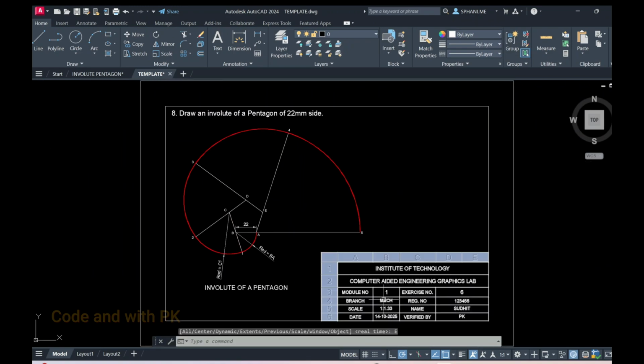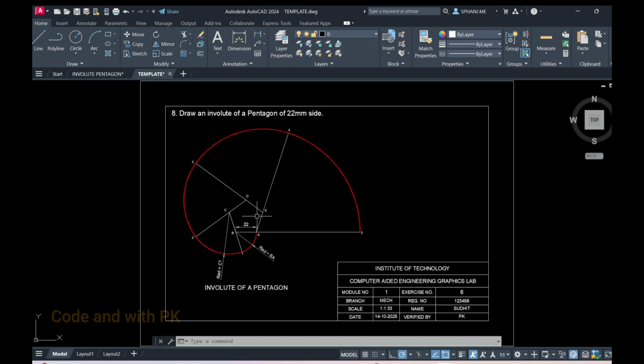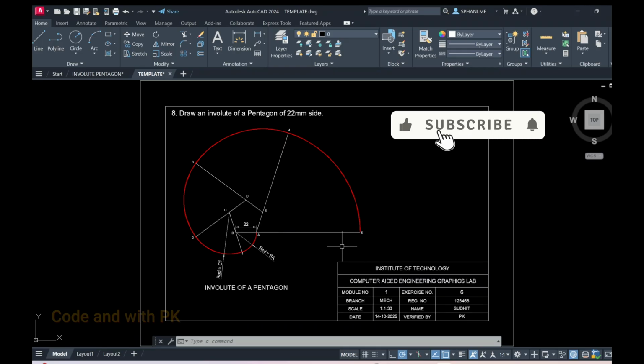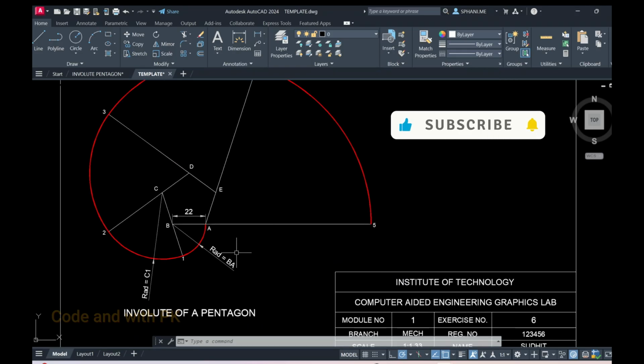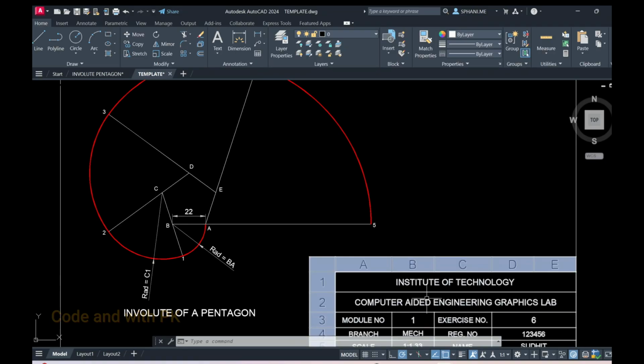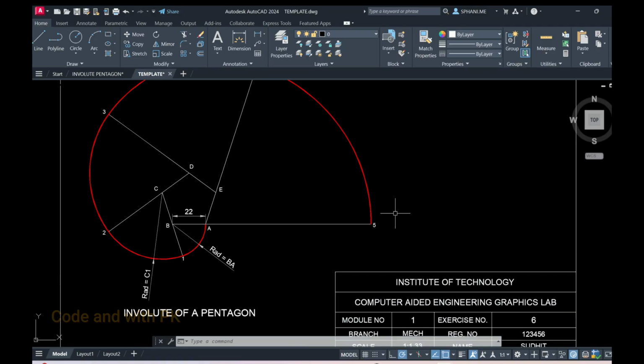If you enlarge, then you can write 2 is to 1. If you want to write your scale factor, 2 is to 1. Here we are reducing, 1 is to 2. So every 2 mm line is converted into a 1 mm line. Every 1.3 mm line is now converted into a 1 mm line.